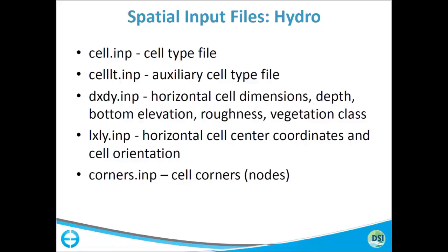If you look at a model and you turn off the corners and you zoom in, and it's not purely orthogonal, you're going to start seeing spaces between the cells. All that to say that this provides a way to make the presentation of your maps look a little bit better, but it is also quite useful in trying to evaluate model behavior when you're looking at orthogonality issues.